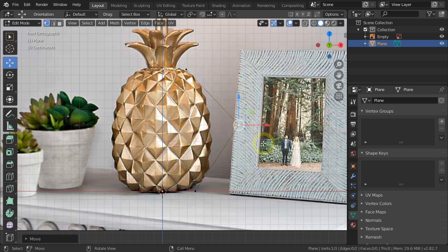Next, to curve out the vertices, we are going to use the vertex bevel command. But before we can do this, let's determine how many segments we actually need based on the number of these diamond shapes. We have 1, 2, 3, 4, 5. We need a total of 11 segments.